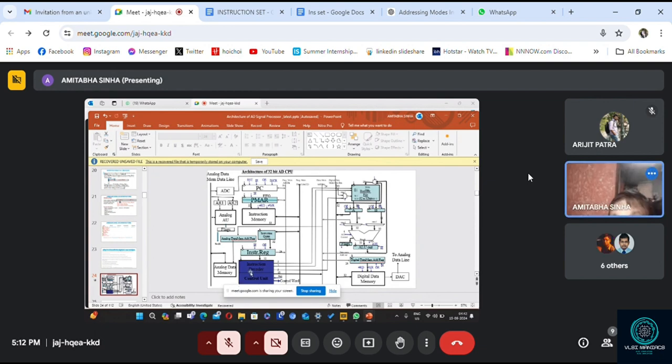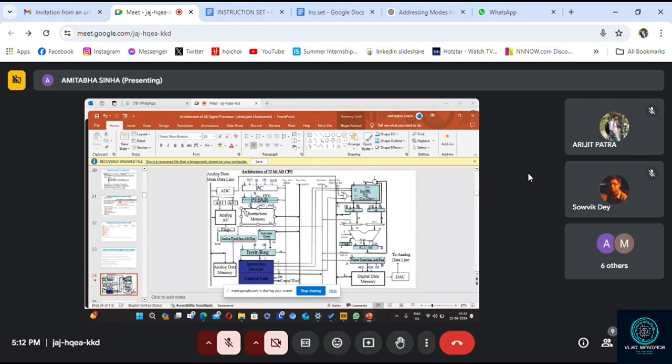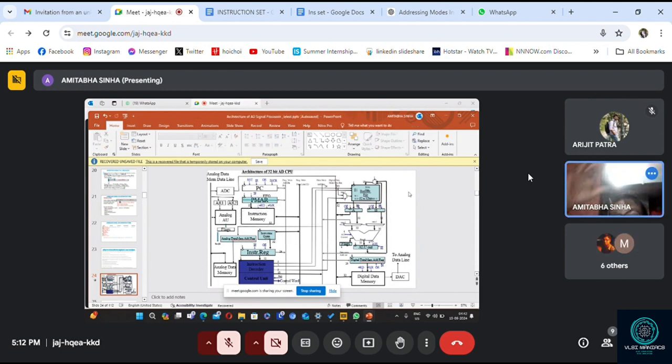Now, there is a block diagram for memory instruction. This is an instruction memory. Have you seen that instruction memory? Yes, sir. Now, instruction memory holds what? It stores the instructions. What is the instruction format for this CPU? 32-bit. Each instruction is 32-bit, 8 plus 24. The address size will be 24-bit, because you have 24 address locations. Is it okay?